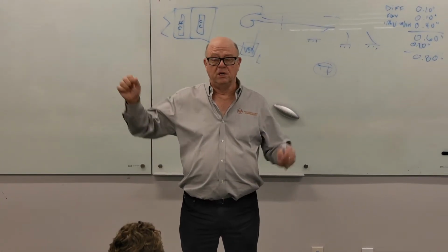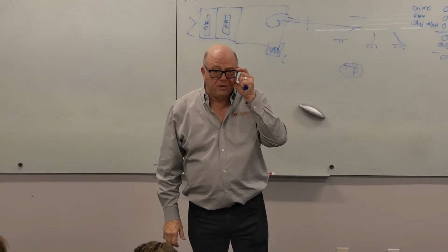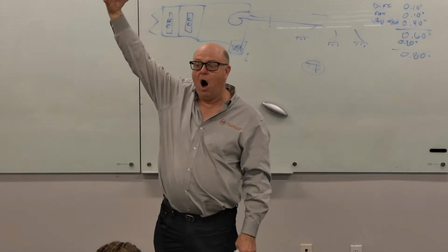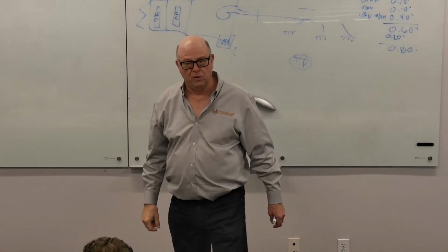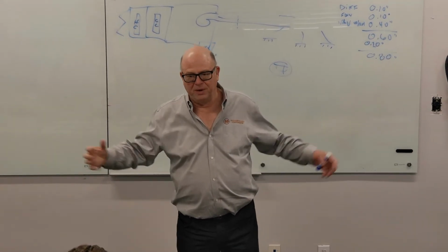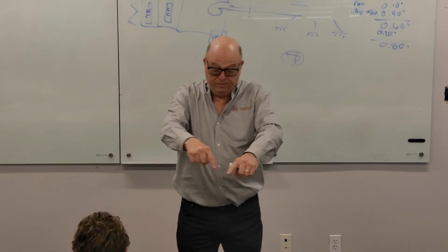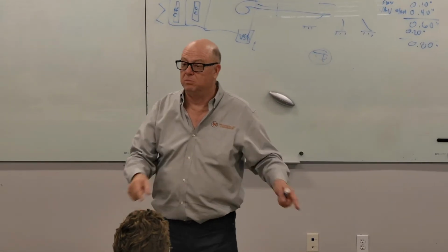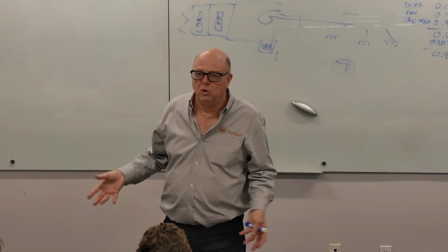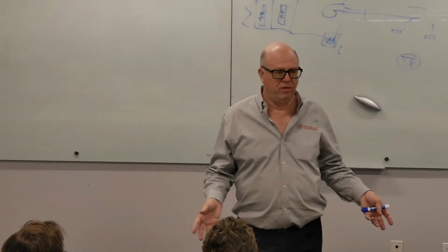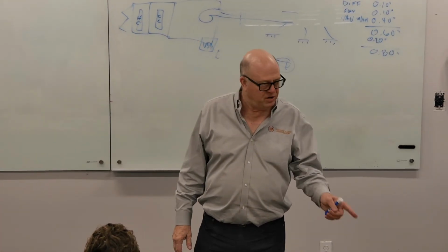And it's not just stages where that's true. It's also operating rooms. You may never have thought about this, but the typical OR with the honking halogen lights just over the shoulder of the surgeon, they didn't just dump heat into the room. They were putting radiant heat on the back of the surgeon and whatever nurses were at the front, the anesthesiologists probably too. Okay, all of those people were getting radiant heat, and that's why they wanted to keep the room as cold as they could get away with. You'll never find a surgeon who doesn't want the room down to about 63 degrees. Did I tell you why you don't go below 60?